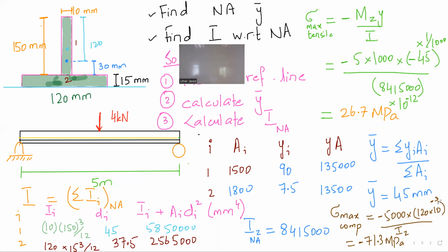Yeah, because we are getting this moment because I skipped the statics part, so I will explain. We are getting the moment of 5,000 as I did RA plus RB equal to 4,000. Then I did minus R. I took this point and I took the summation of moments as 0, and then I found 2,000 here, reaction, and 2,000 here. Then I started making cuts.